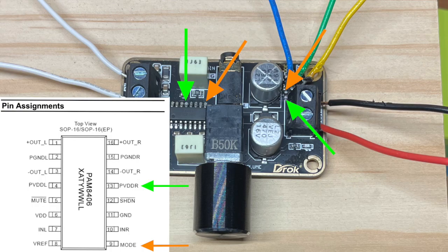When the pins were connected, the amplifier was always selected as Class D, which defeated the whole purpose of why I wanted to get it. So after removing it, the pins are now separated and I can control them independently. I didn't modify the power supply pin, but now I have access to the mode pin.